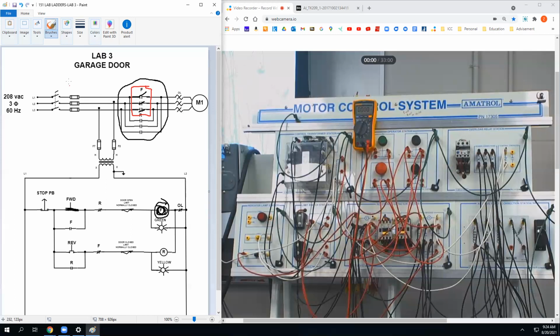So when I put the positive lead somewhere and I put the negative lead somewhere on the line side, let's say positive here, the negative side, I need to find a good neutral. The other day, I don't remember who, but at least 1 or 2 of you were checking voltage in the power circuit to this neutral. And that's no good. Why?